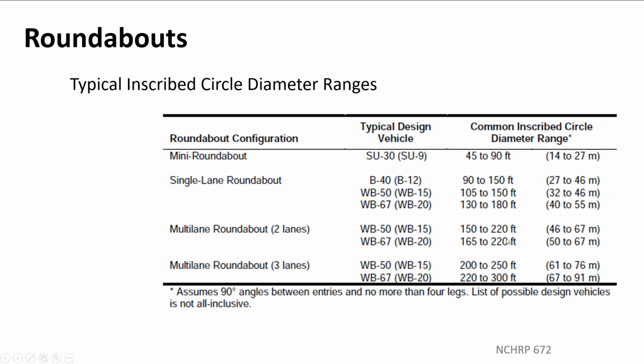Right, and we still get pretty good efficiencies in multi-lane roundabouts. You don't get twice as much efficiency as you would with a single lane, or 3 times as much. Nor do you get 2 or 3 times the capacity if you add a second or a third lane on any roadway through there. It's not equal. Each lane isn't equal. The ones you add next don't have quite as much capacity as the original one did.